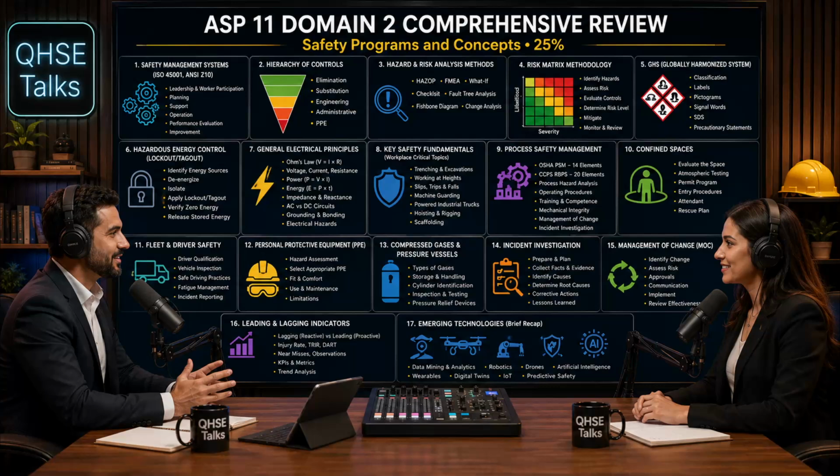What are some of those elements? It mandates deep mechanical integrity programs, process hazard analyses, and strict contractor management, among others. And the CCPS risk-based process safety model expands on that with 20 elements, focusing heavily on building a robust safety culture and operational discipline. It acknowledges that having the binders on the shelf just isn't enough, right? The organization has to actually live the procedures.